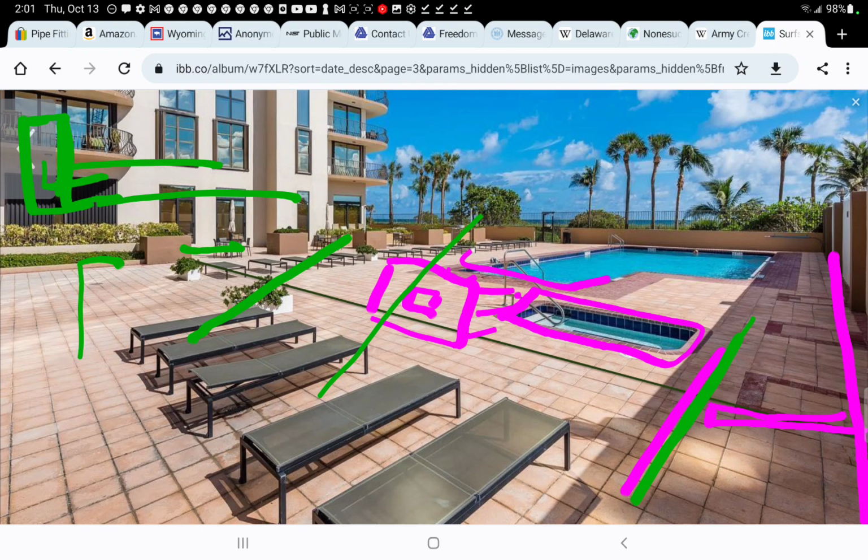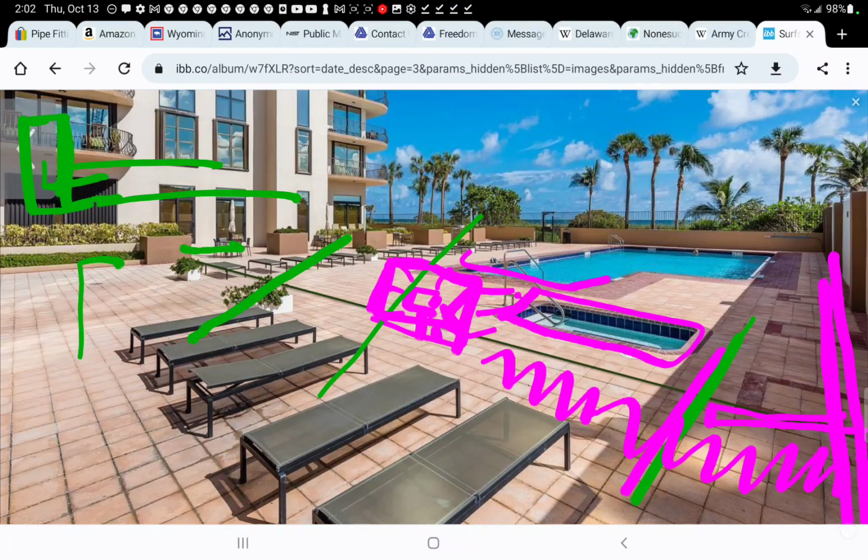Okay. But in the top deck, we'll go back to the pink, the overlay deck, it's because it's over that column, this is a more rigid area. That's why I made up my critical shear zone a little bit stronger, because it's over the column there, plus the deck below it. But between here, it's tributary. Oh, wait a minute. As it gets to the wall, it's still tributary. It puts us in shear also over there, just like you saw in the garage, except this is a continuous supported structure. All right, it's an infinite supported structure at this point.